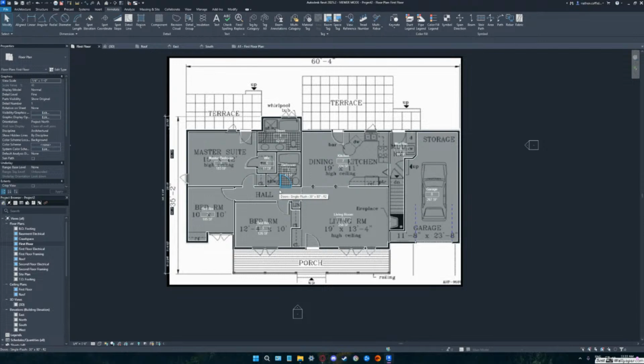Now, what I was going to tell you was most people would be saying, Brian, I don't want to dimension yet. I want to go put in my kitchen cabinets, and my refrigerator and my shower and my bathroom stall and my walk-in closets and all of that kind of stuff. And then I'll do the dimensioning. And here's the problem I would warn anyone that might be watching this, and you yourself, Nathan. If you put all of that stuff in and you start dimensioning, just like you dimension to the handrail, you're going to find you think you're dimensioning to the wall behind the stove, but you're actually going to be dimensioning to the stove, which causes things to work completely different.